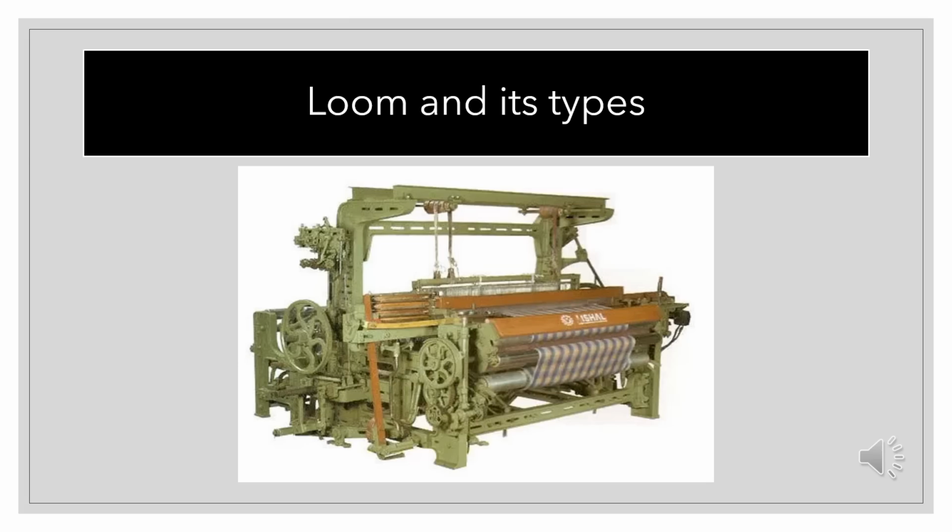Projectile loom. A weaving machine in which the weft thread is gripped by jaws fitted in a projectile, which is then propelled through the shed. It has a small hook-like device that grips the end of the filling yarn. It is sometimes called a missile loom as the picking action is done by a series of small bullet-like projectiles which hold the yarn. Rapier loom. Rapier looms are machines in which the means of carrying the weft through the shed is fixed at the end of a rigid rod or in a flexible ribbon, this being positively driven.